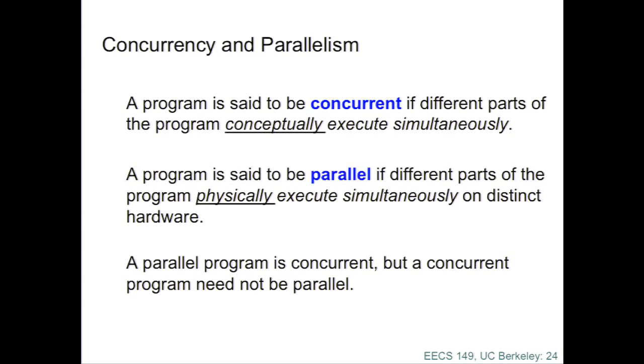And from the perspective of debugging these programs, it really doesn't make any difference whether you have parallelism or not. So, for example, suppose that you had a multi-core processor where two cores share the same memory space, and your interrupt service routines are always executed in core number 2, and your main program always executes in core number 1, right? Then your main program doesn't ever get its timing disrupted. Actually, it does because of contention for the memory system, okay? But if you pretend the memory system doesn't have any contention, which is not a good choice, but nevertheless, then at least you get less disruption of timing. But the possible interleavings of the actions are still just as complex, whether it's parallel or concurrent, okay?